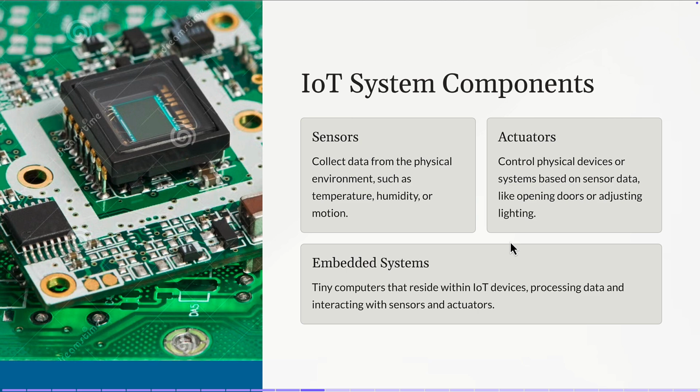Sometimes, if an event is detected, you may need to activate it for a longer time. But say I want to sense temperature: the temperature is not going to change every second. If you want a sensor to sense climate temperature, I can activate it once an hour, because usually the difference of temperature in 1 hour is going to be small.